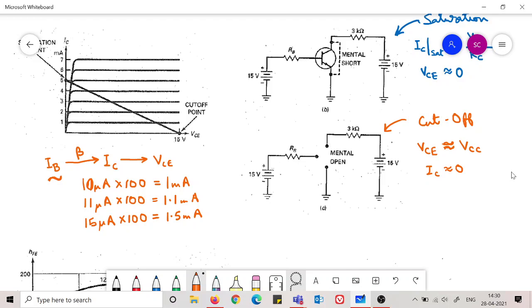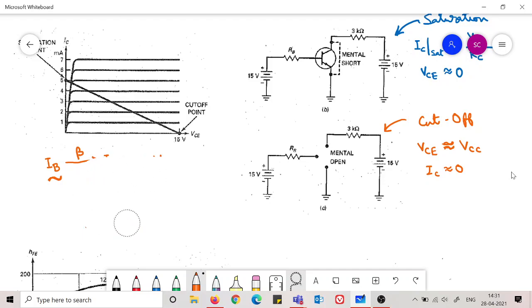This is also very evident from this graph that you are seeing. If you change this value a bit, since this load line is so much slanted, obviously it will be slanted, the change in IC is quite a lot, and the change in VCE will also be quite appreciable. This gives rise to a phenomenon which we call the moving Q point.